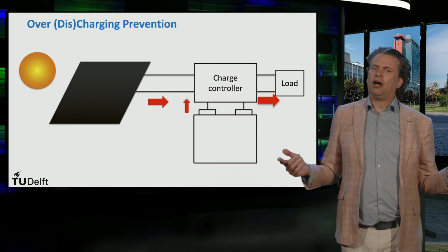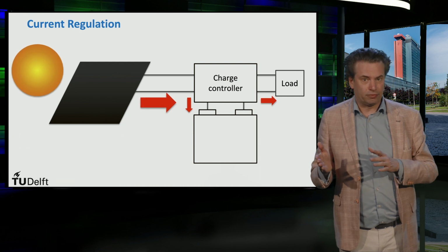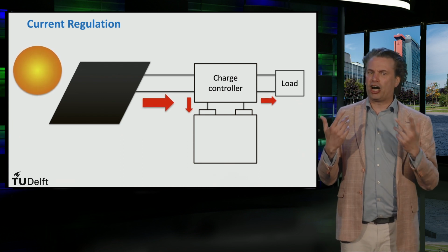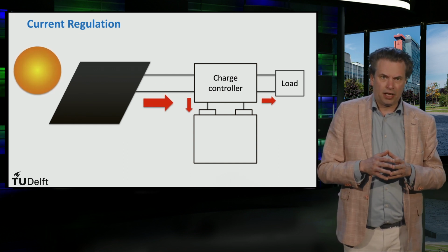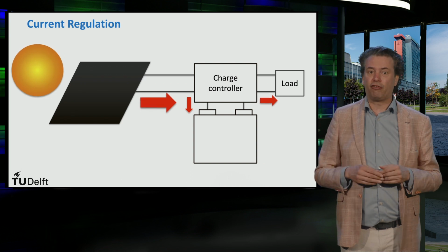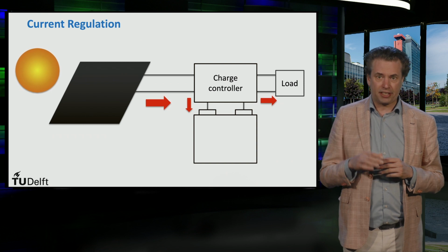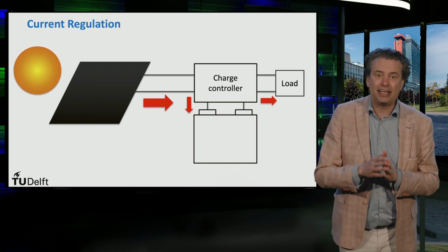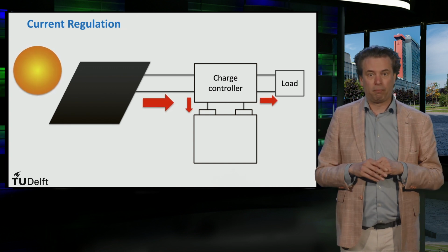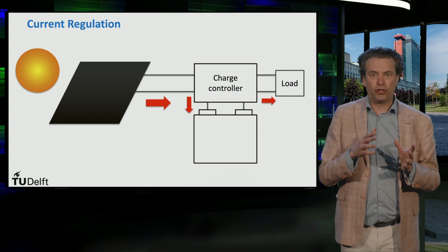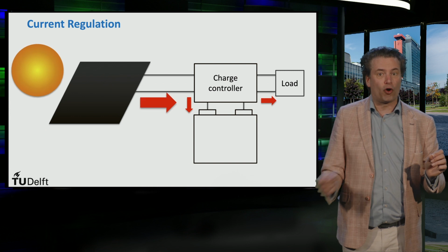Another function of the charge controller is current regulation. Consider a battery which is being discharged at a faster rate than its nominal rate. This leads to a reduction in the efficiency of the battery as well. But a charge controller with a proper current regulator can be used to control this by maintaining the rate close to its C rate, which is the battery's nominal parameter. The charge controller does this by imposing limits on maximal current flowing out of or into the battery.